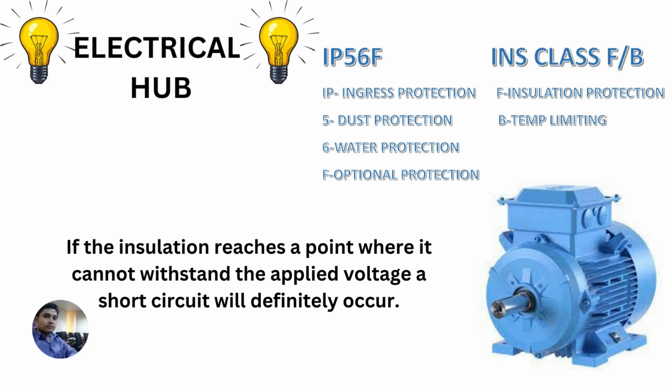If it goes beyond that, to 110, the life becomes 2,500 hours. So the degradation is very sharp. If the rise of temperature goes to a point where the insulation cannot bear it, it will get damaged and a short circuit will definitely occur.